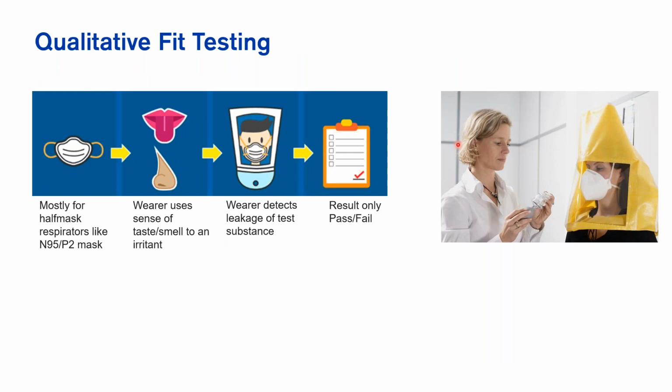However, the fit test you should conduct annually, and you have to go through a tester. The tester will put a hood on the wearer. Before starting, you are tested on a chemical which is approved for testing. You'll be tested on whether you feel the chemical's presence. And if you pass it, after this you will rest for 15 minutes. You'll not don your respirator.